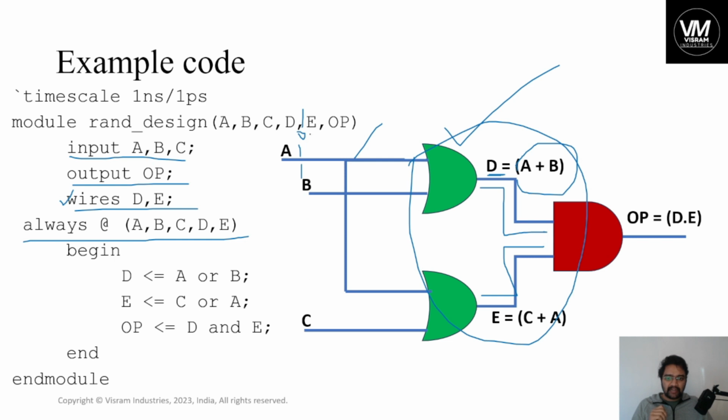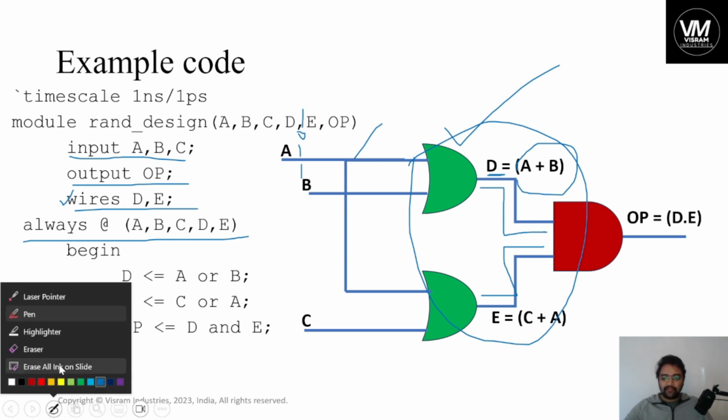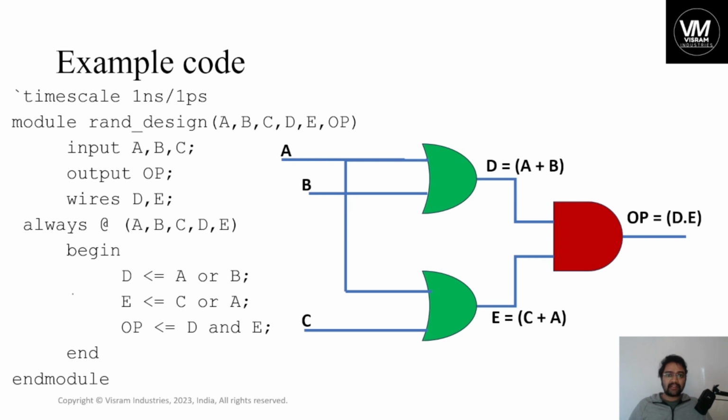So all the data input ports or variables should be changing, and for that continuous functionality, if it changes, it should work. That is how we declare always @(changes of the inputs). So on changes of the inputs, you need to start processing the entire thing.